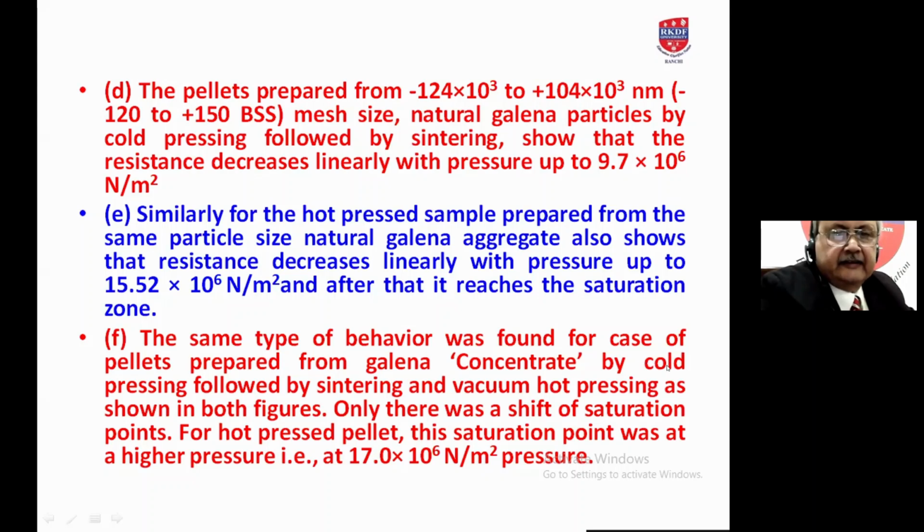particles, that is cold pressing followed by sintering, and the vacuum hot pressing also. There, for the hot press sample, the saturation point was at a higher pressure, that is 17.0 × 10^6 Newton per meter square pressure.